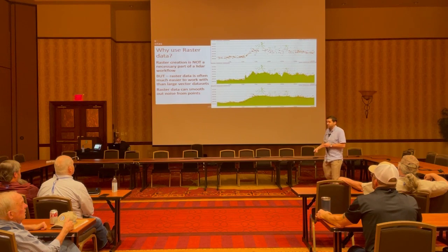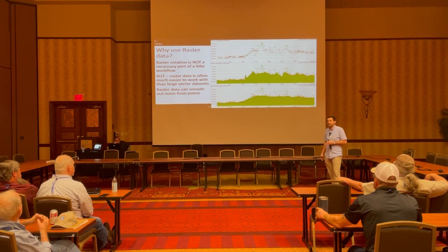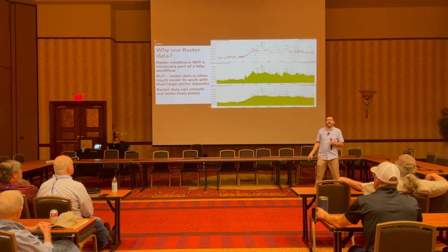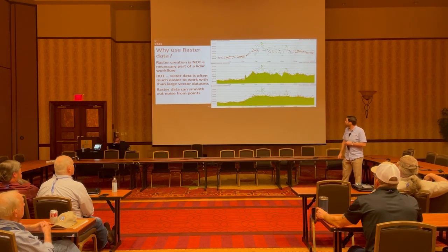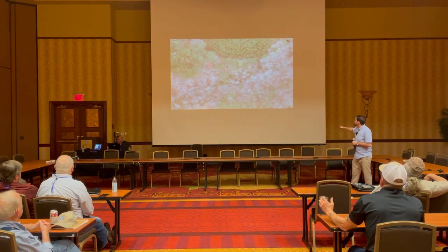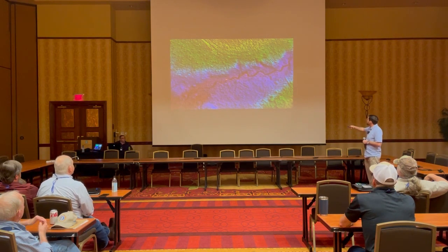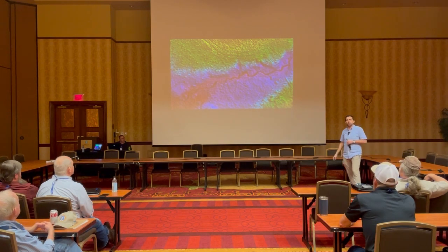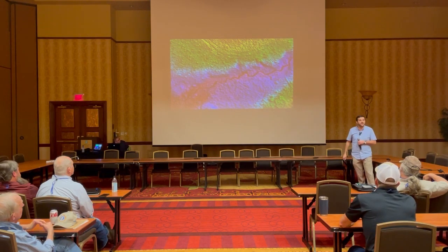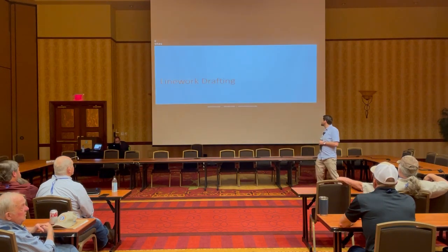This is especially easy to do because drone LiDAR has such ridiculously dense data, thousands of points per meter, as opposed to state-provided aerial LiDAR, which is going to be a much more granular, much lower resolution product. And that's how you can turn something like this, wooded forests, into something like this, where you can clearly see the exact banks of the stream. You can see the tire ruts from where a truck was driving underneath the trees. You can see fallen logs, because that is how good this is through the trees when you actually rasterize this data and get a good surface out of it.